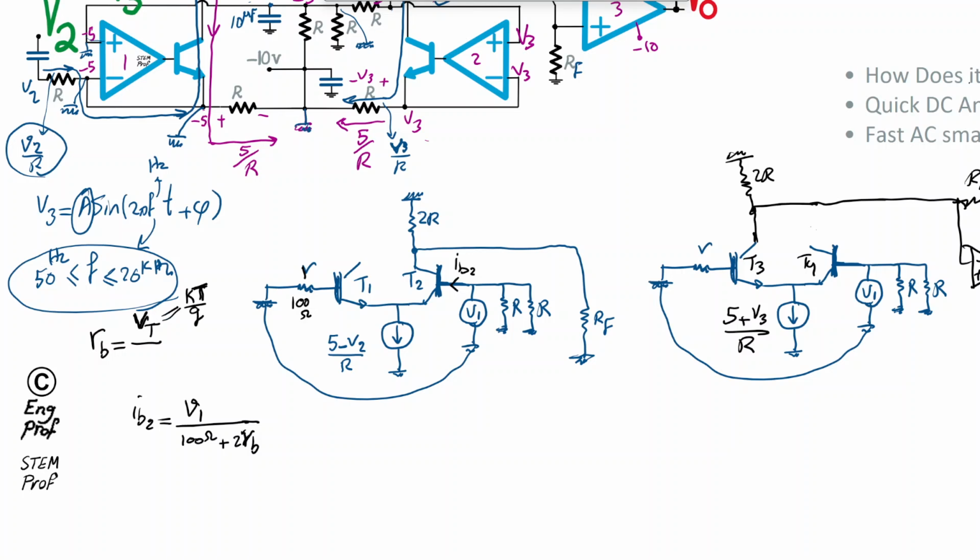T is the junction temperature in Kelvin for the PN junction of the BJT transistor, and Q is the electron charge. So at room temperature, when T is roughly 290 degrees Kelvin, corresponding to about 17 degrees or close to 20 degrees, this number is something on the order of 25 millivolt for the thermal voltage. So that's just giving you a sense.